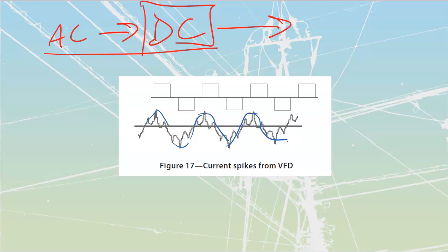They list out a bunch of machines after this that do have high amounts of noise. We'll get to the power factor correction capacitors in a second, but machines that cause noise: arc welders, huge amounts of noise. You've got to oversize your neutrals with those things and oversize your conductors, just because we're going to get such rapid, dirty power happening inside there. Computer equipment, anything where we've got servers or large office buildings full of computers. We've got a couple that are particularly bad that deal with high voltage, where we're trying to ionize stuff inside of them.